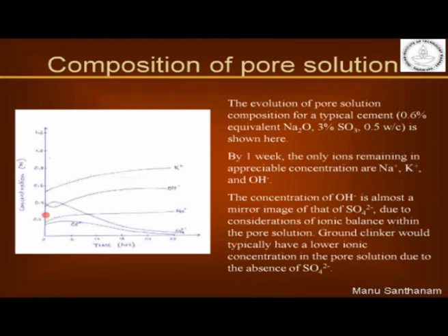Sulfate, in the beginning it is high because your sulfate phases are dissolving, but then as sulfate gets converted to ettringite and monosulfate, the sulfate keeps getting consumed and becomes almost zero in the system. So if you take a concrete that is hardened and you press out all the water from inside the concrete, and do an ionic analysis of the water, you will find that it only has sodium, potassium and hydroxyl ions,